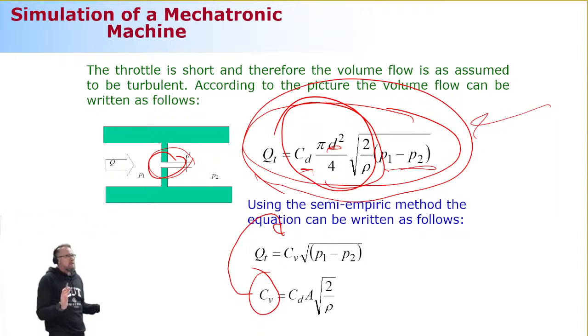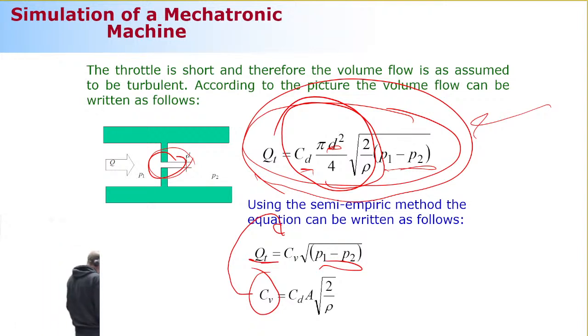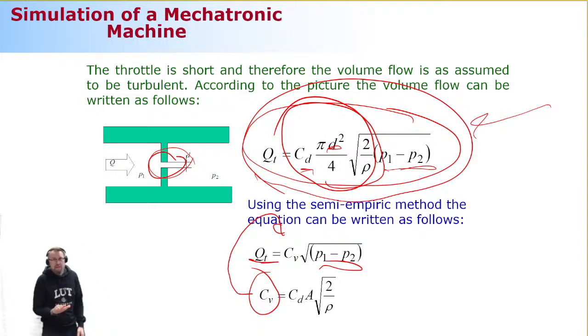Why do we do this? Because now we have a clear relation between the pressure difference and the flow rate. And this is exactly what is typically offered by manufacturer's catalog. I understand that you are not getting excited yet, because this is such a simple component. Such a simple component that it is not that much work to model this, even when defining this throttle diameter. Yes, it is possible, but this becomes extremely handy when we look at components more complicated than a throttle valve.